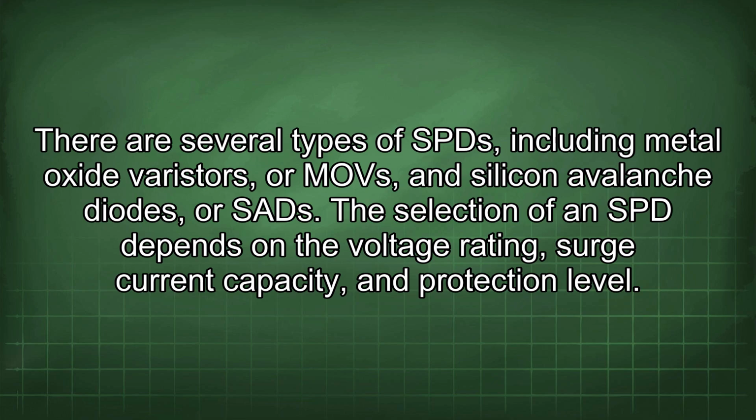There are several types of SPDs, including metal oxide varistors, or MOVs, and silicon avalanche diodes, or SADs. The selection of an SPD depends on the voltage rating, surge current capacity, and protection level.